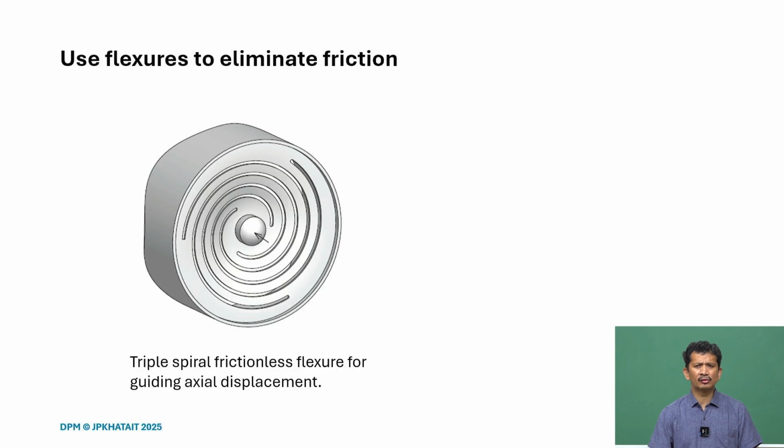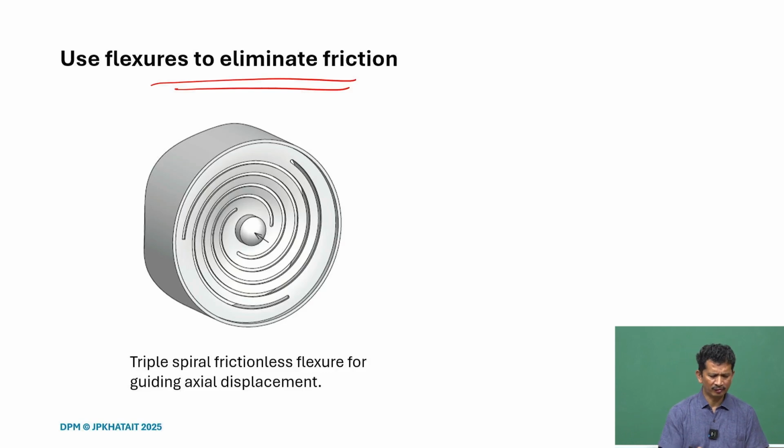One of the ways to address friction related problems is to just eliminate it. Many times it's not possible, but wherever possible, can we do that? What we realize is that in today's time, in many machines or products, the range of motions is very limited. And if that is the case, we can always remove those conventional joints using rolling element bearings, and replace them with flexure elements.